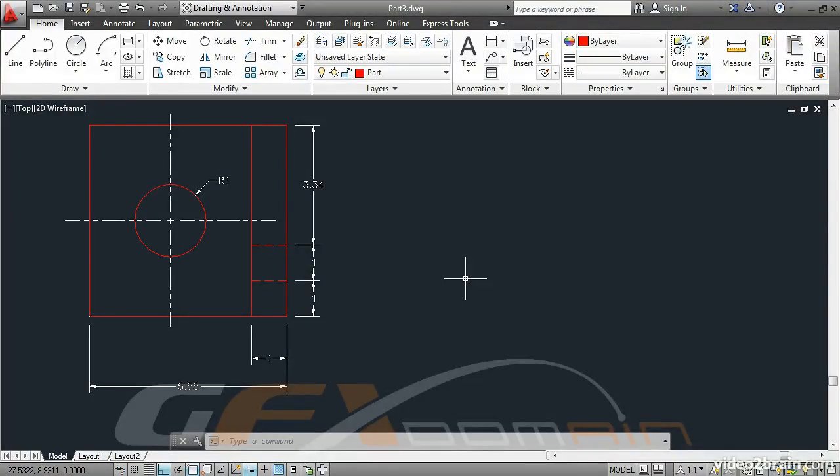In this lesson, you will learn how to use object snap tracking and will gain more drawing experience with a mechanical part project. Object snap tracking allows you to infer snap points which aren't on other existing objects. You can use object snap tracking to zero in on the significant points implied by the geometry in your drawing. Open the Part 3 project file.